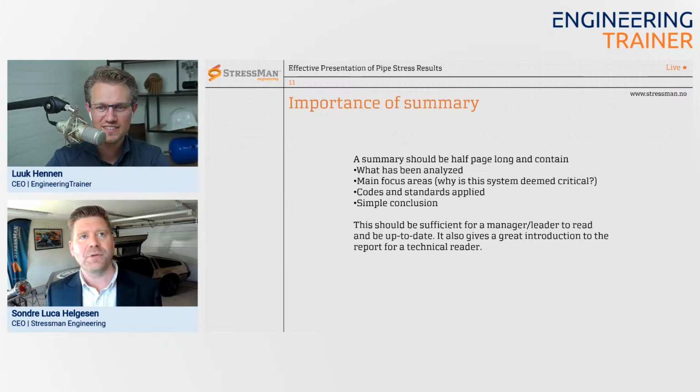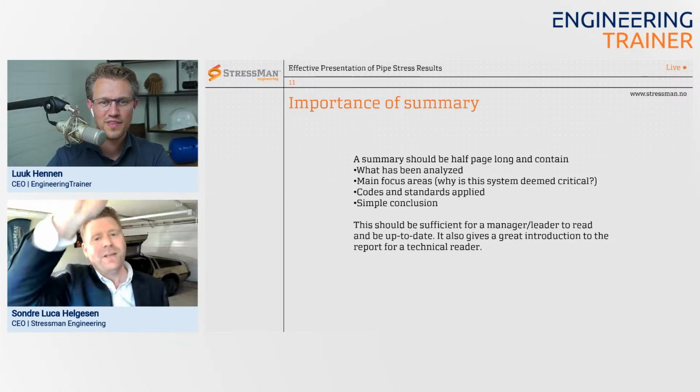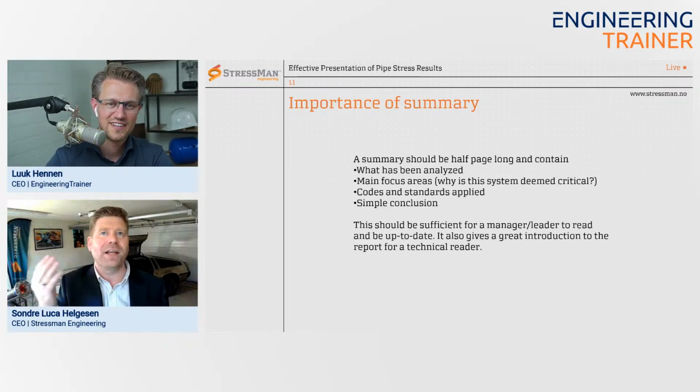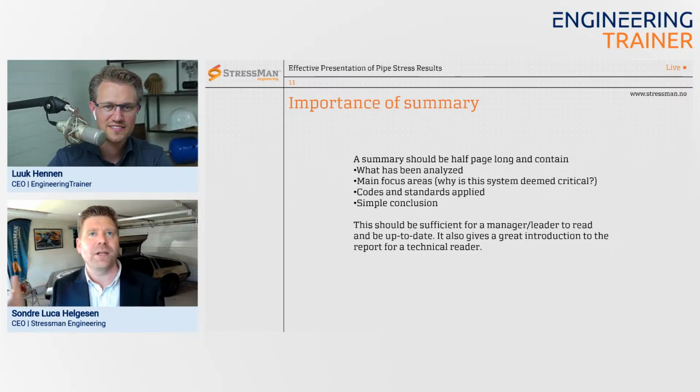To make a pipe stress model that you can use, even though you're not going to touch those pipes in the roof, for example, but you're going to connect something on the next level to this pipe work, and at least having like 3 to 4 pipe supports in various directions, to have some kind of limitation to where your impact will stop impacting the existing system.